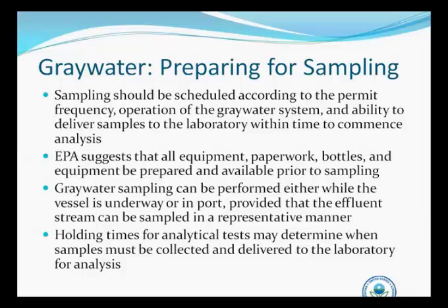So in preparing for sampling for gray water, it's important to determine the frequency of your sampling and the best time for collection. You want to be familiar with the operation of your gray water system and also be confident in your ability to deliver samples to the lab in time to commence analysis.